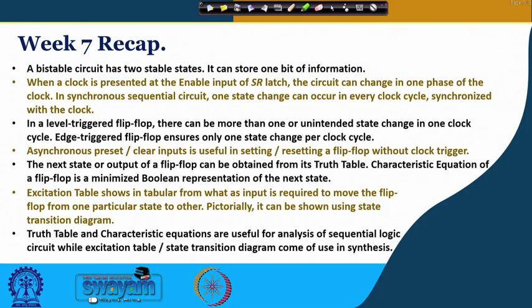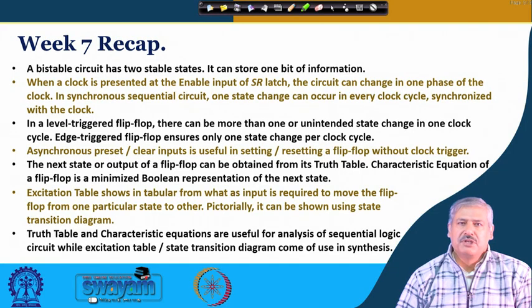Its various representations in the form of truth table, characteristic equation, excitation table, state transition diagram, and then we understood the issues that could be there with level triggered flip flop, for which edge triggered flip flop is advisable, which ensures only one transition per clock cycle.